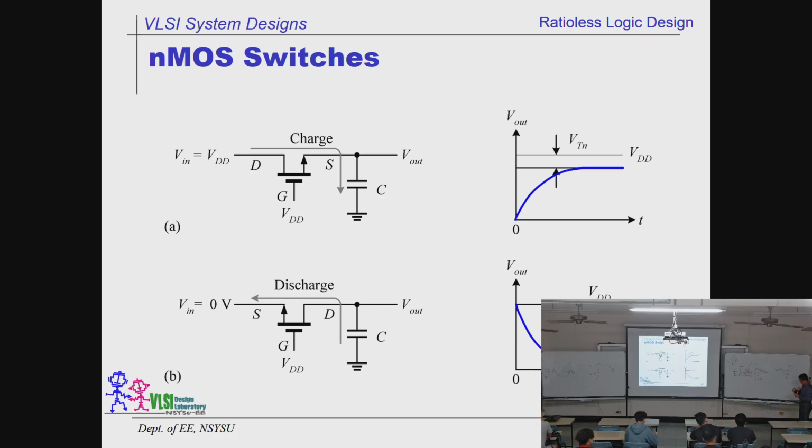It's perfect. Now the problem is a lot of students mess up at the beginning of design. When they say, I have a VDD at the gate, this won't be turned on automatically. No, it's not. In this case, if the terminal here is not grounded, it is VDD.